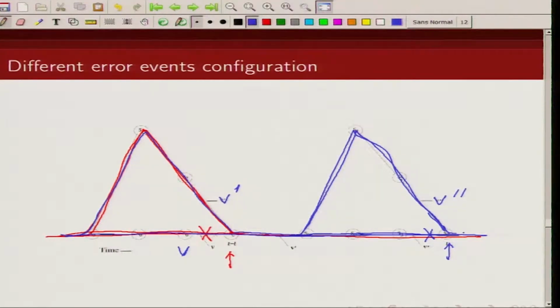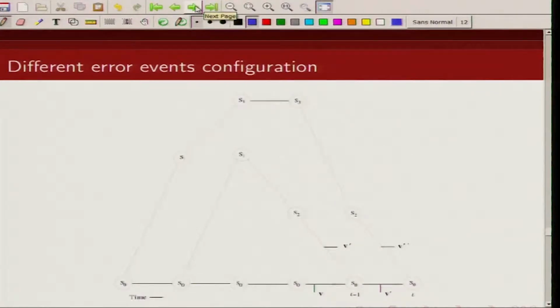So, the point which I am trying to make is, whenever you have these kinds of multiple error events, you can always upper bound your event error probability by the error probability of the first event error. When you decide in favor of this particular code word, that means this has a better metric corresponding to v hat or v. So, we can upper bound the probability of event error by first event error probability, and this could have multiple configurations.